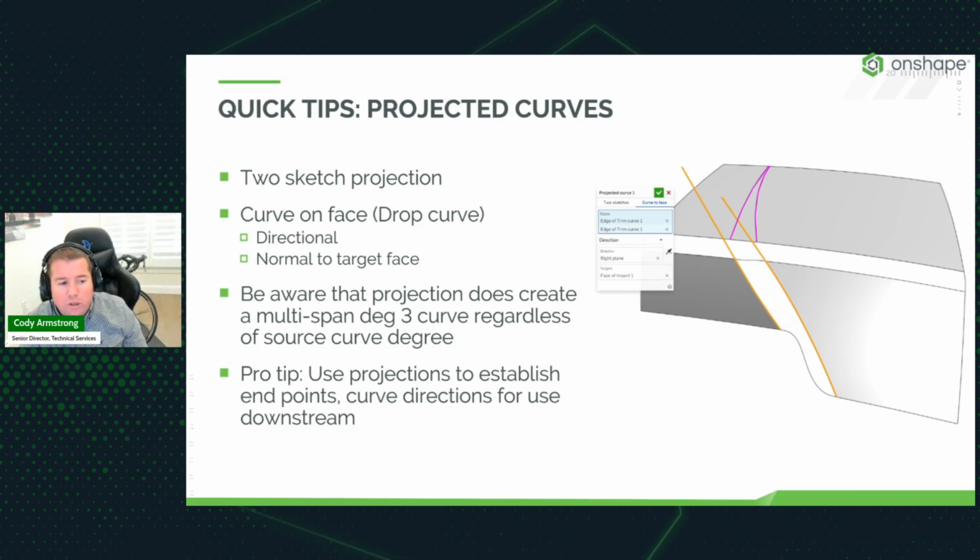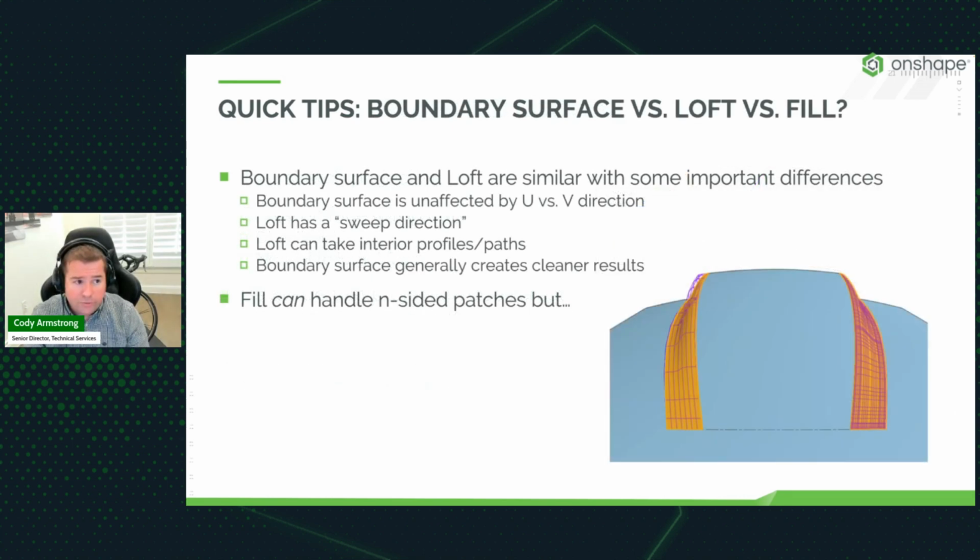So just be aware, using projections is great for certain scenarios, but using projected curves and then splitting and then using the resultant split edge to define other geometry is a practice that we've seen can lead to problems. You should be cautious when using it. So projected curves definitely have their place. I think they're useful for defining those endpoints and other scenarios. I don't want to make it sound like they have no other place besides that. But for advanced surfacing, where you really care about the cleanliness of the resulting geometry, you want to be cautious with projected curves.